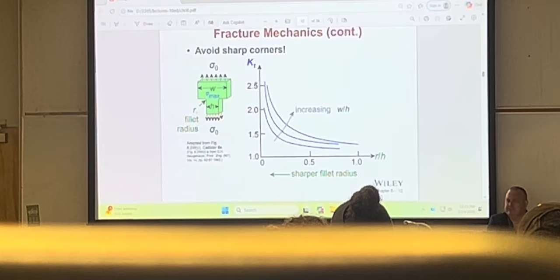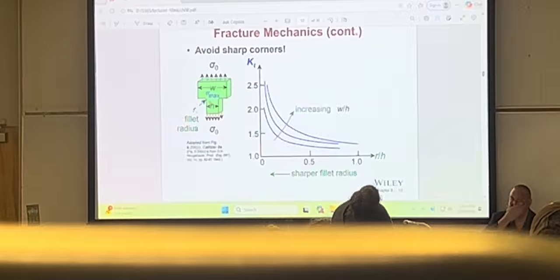So whenever you do the design, you want to make this radius as large as possible. You want to make this transition as smooth as possible. And if it can be avoided, try to avoid it.